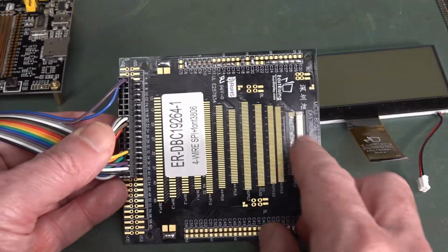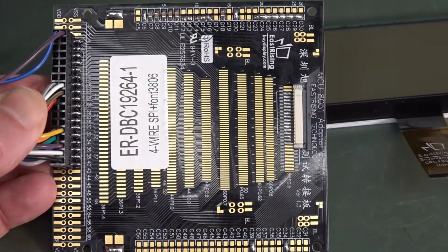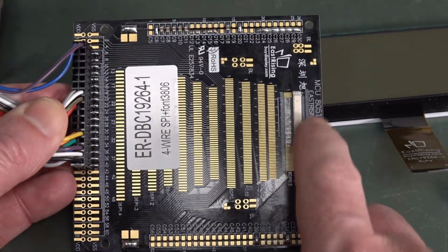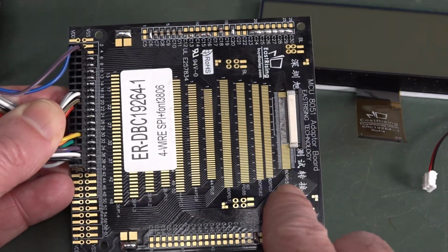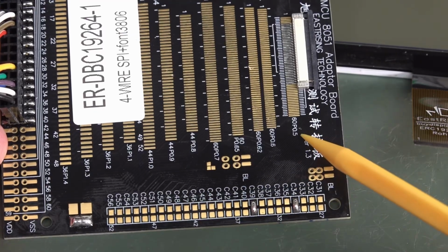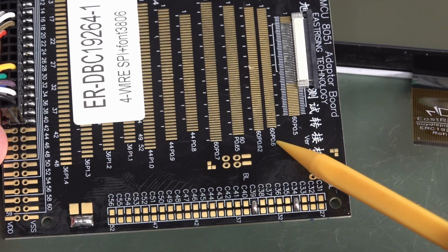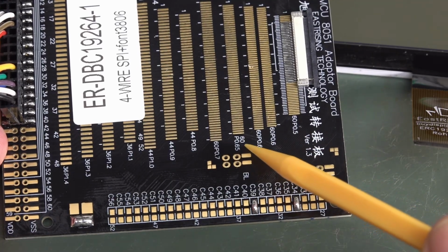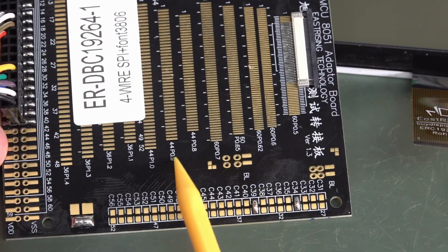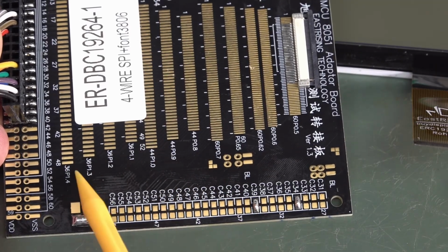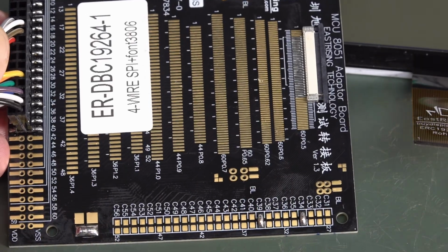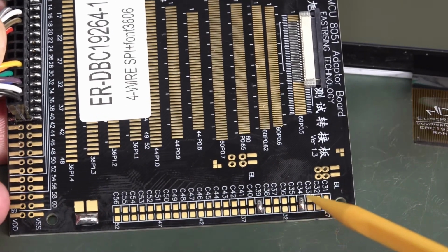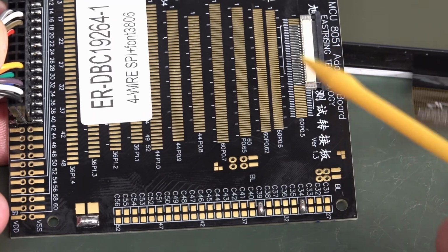And then it comes with an interface board like this, and you can see that they've already pre-programmed on the 36-way flat flex connector, 0.5 millimeter pitch. So these are different pitches. We've got the 0.5 we're using here, we've got 0.6, 0.62, 0.65, 0.7, 0.8, 0.9, 1, etc. So we've got all the different pin pitches here. So this is a very handy board, and you'll notice that you can also tie any of the pins.